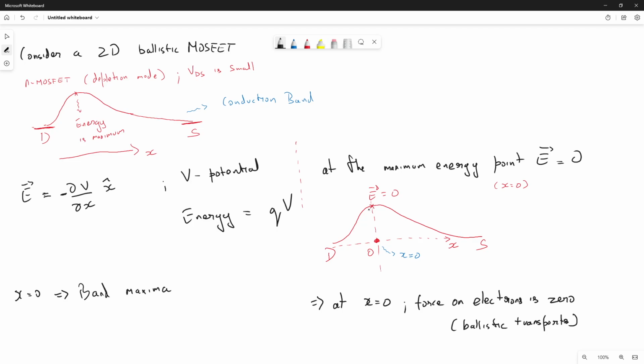There is no channel per se in a BJT; what we have is the base region, where we inject a very large amount of minority carriers. What we call the minority carrier in the base is actually the majority carrier in the collector and emitter regions. So there, this distortion is achieved via charge, whereas in field effect transistors, it is achieved via an electric field, or rather an external potential.